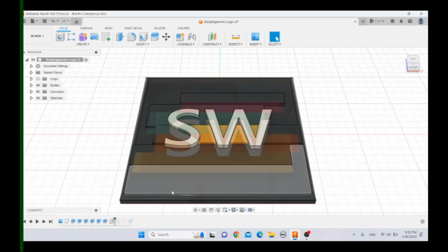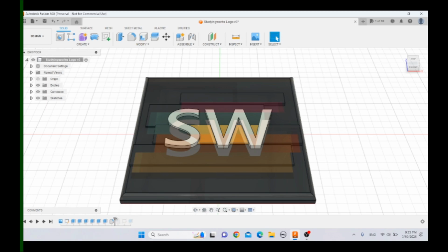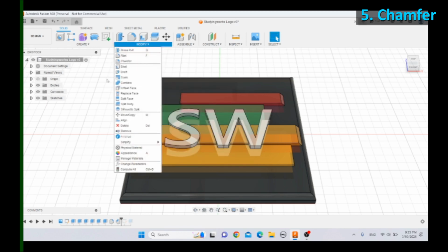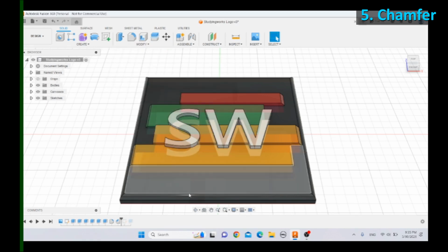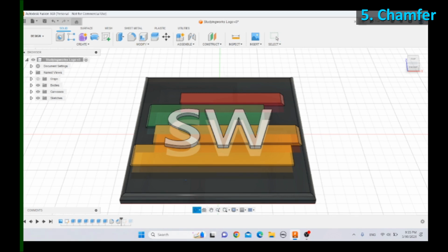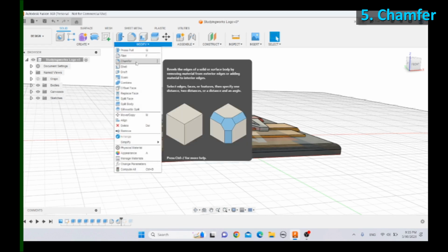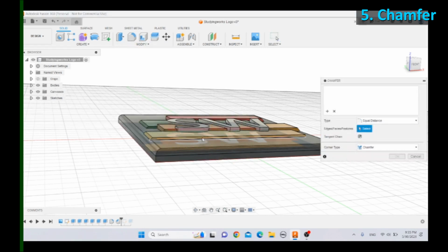As so. Now moving on to the next part, chamfer, which is essentially similar except with a flatter edge cut, as you can see right around these corners. To use this chamfer, you go to modify, click chamfer, click an edge, and then move.